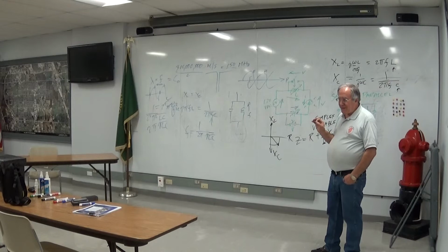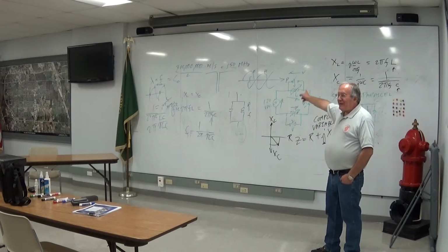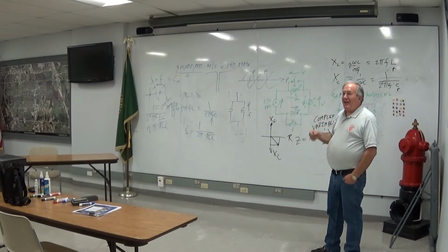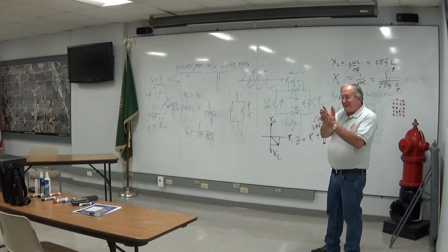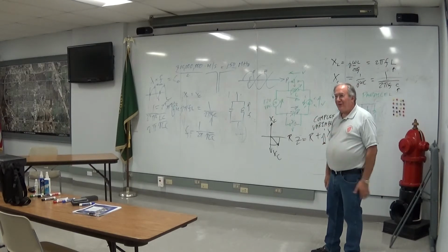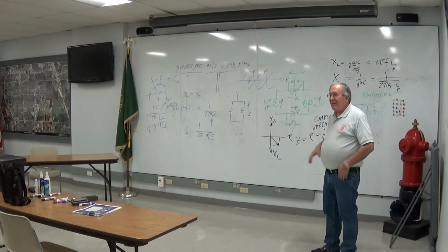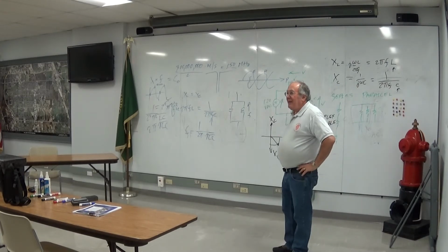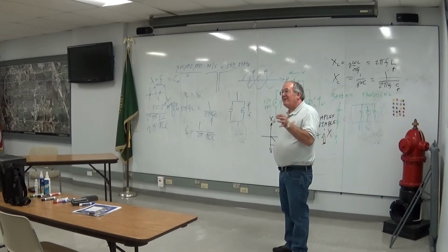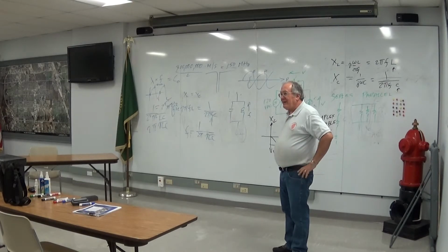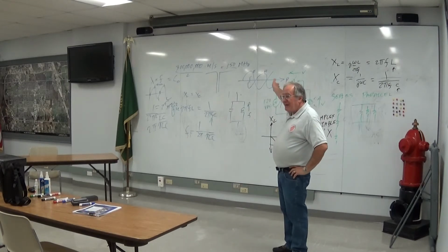62.5 microseconds means that if the radio wave had to bounce off of a different building, it might show up a few microseconds late. That's enough for the picture to shift over, the ghost image to be an inch or two from the primary image. That's why you saw it. So you can actually visualize things that happen in millionths of a second if you got the right kind of medium. We've got a right kind of medium device for doing it.